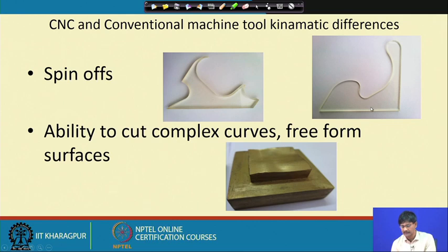Okay, similar thing. But what we did was, we simply made a program for the cutting of this one, and the tool was automatically guided all through by the program. How was this done? Corresponding to each and every movement, the interpolator sent a different pattern of pulses to the circuit which was controlling the movement of the table, and accordingly it was done. Everything was done automatically.